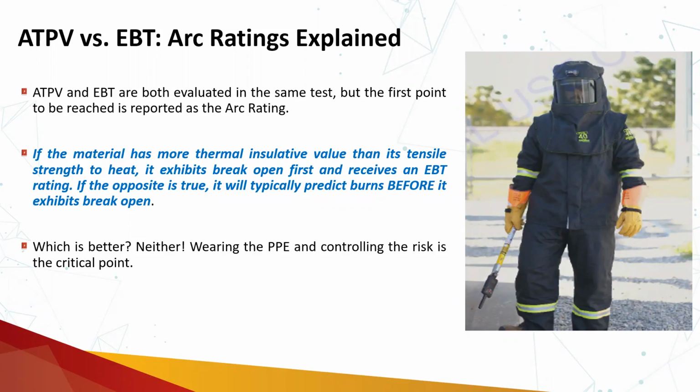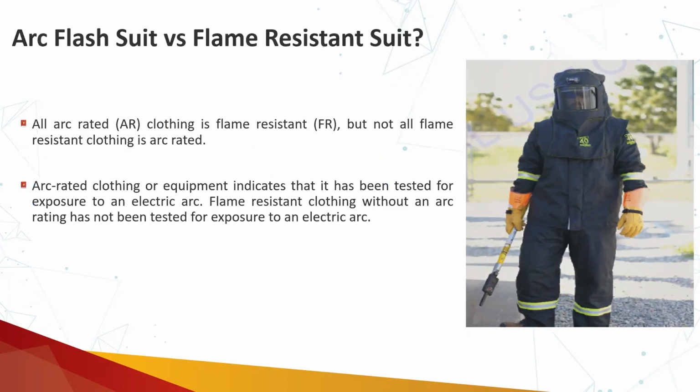Whether that arc rating is derived from ATPV or EBT, it's of no use to us. The main thing is that we have to protect our employees, the people who are working. So we will be selecting our personal protective equipment based on incident energy in calories per centimeter square, or the arc rating.